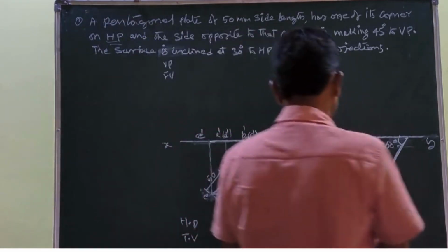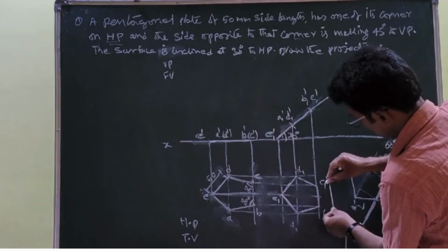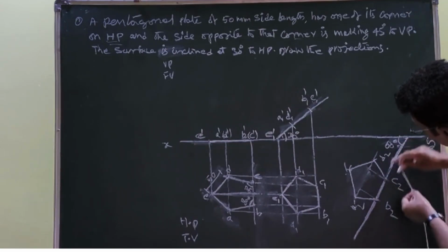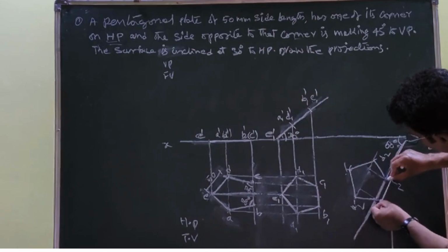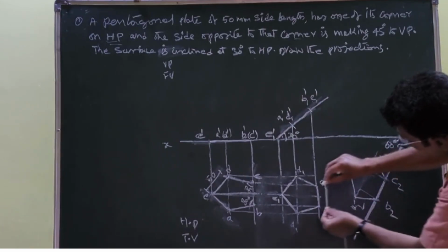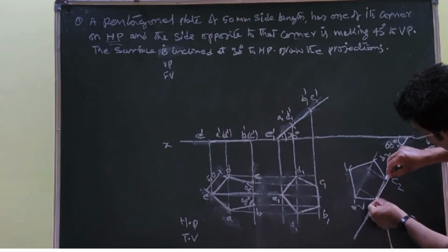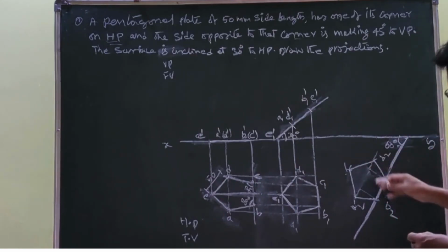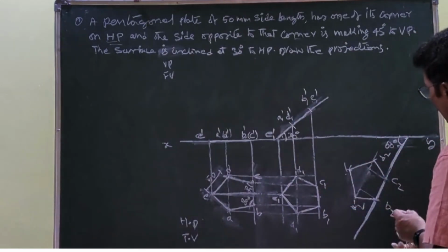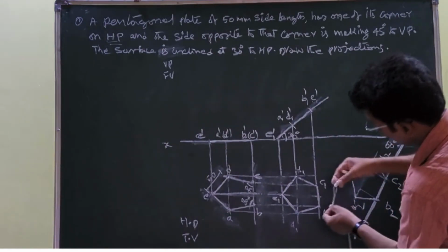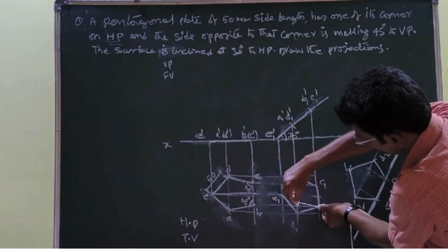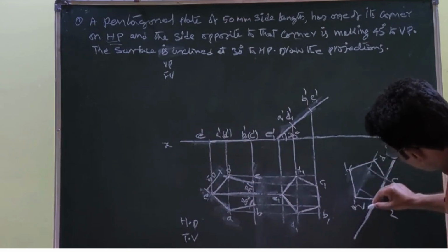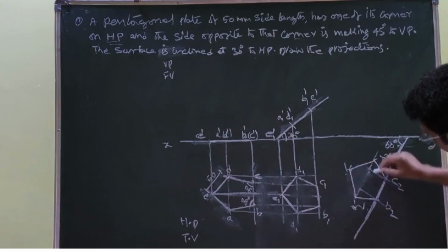Again I am explaining once again here. This is the B2 C2 as a radius at any one point on this line, 60 degrees. At this point you select a point here. Take this distance C1 C2, you cut it here. Then without setting the degrees, you can easily construct. After that you draw the perpendicular to C2 B2, perpendicular to this line.